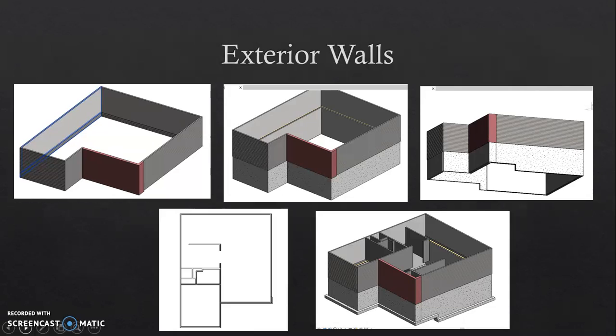So to create the exterior walls, I had to edit properties and materials of the walls that I would be placing in. I had to add in a wall extension, which basically dropped down the materials to below where the original walls were in order to cover up structural materials that made up the floor.